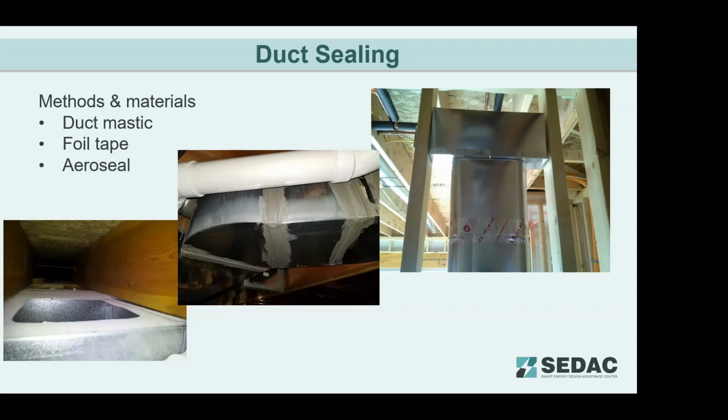And then on the right, you're seeing an attempt to start sealing some ductwork with some foil tape. You can see one of the seams in that wall stack has been sealed up, but the boot above it has no mastic, no tape or anything. So if we were not passing a test, then I would obviously spend some time sealing those up as well.